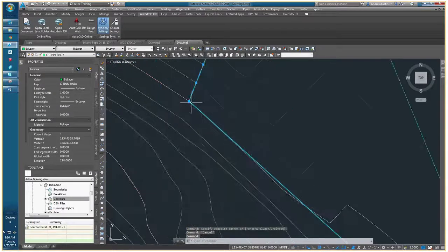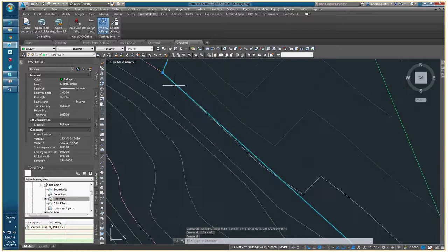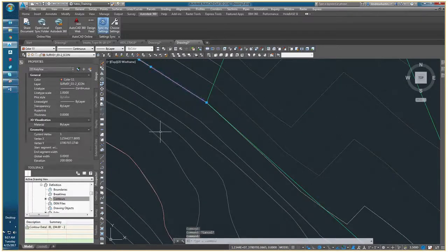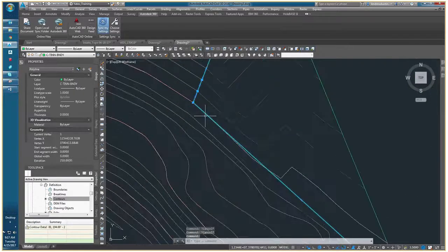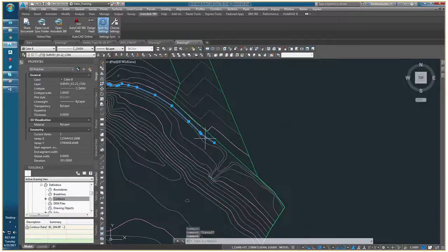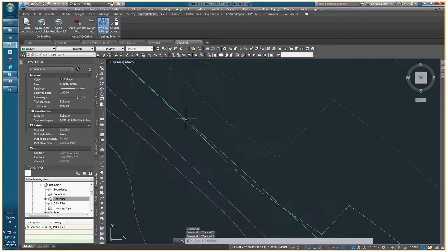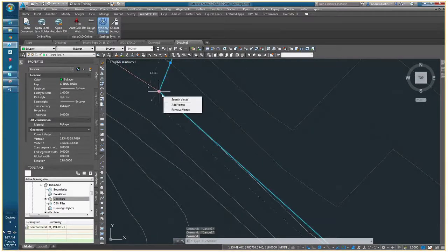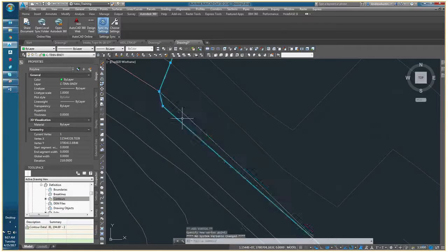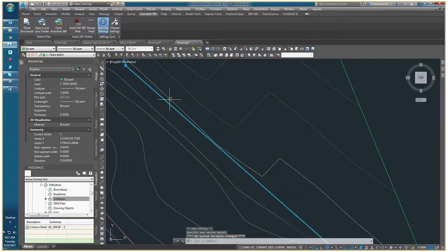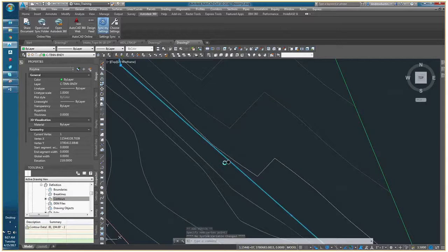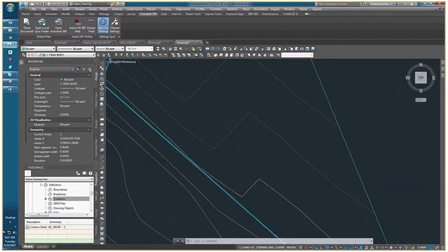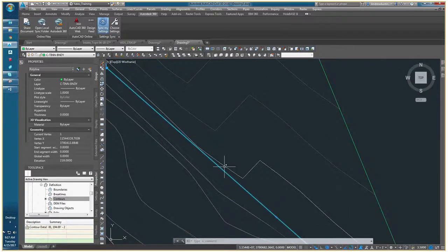But when we get down here, we notice that our boundary is just up above this contour, which is the elevation 200 contour. But we have contour data from the surveyor that goes all the way down here. What we want to do here is just slightly refine this by adding another vertices just below here so that that boundary line goes above our existing contour data and below where there's no contour data.